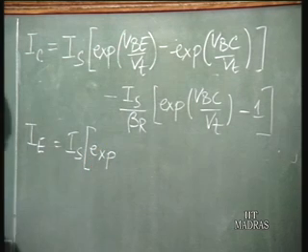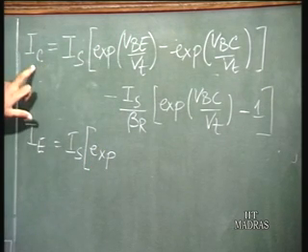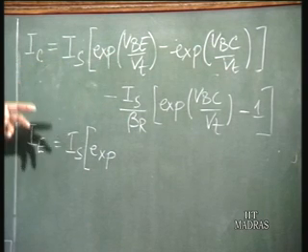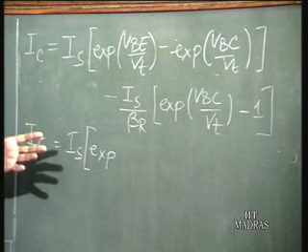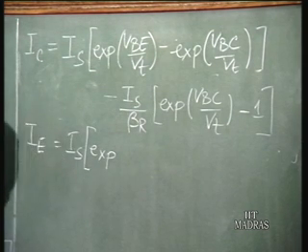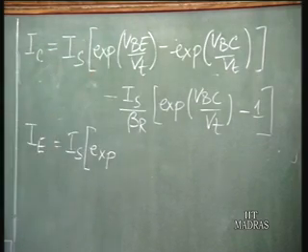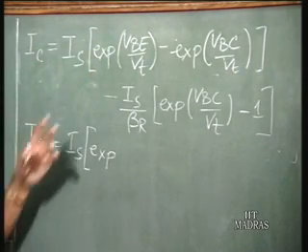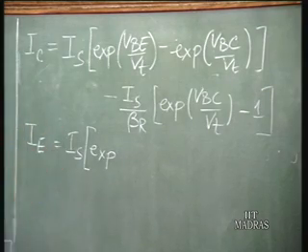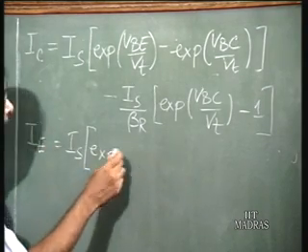This is just plain manipulation. Basically you have to write IC is equal to alpha f If minus IR. So, alpha f If you know from the forward case, when the current is flowing in the forward direction, the IR expression also you have calculated, and then you just write them in terms of Is and the two betas, beta f and beta r.